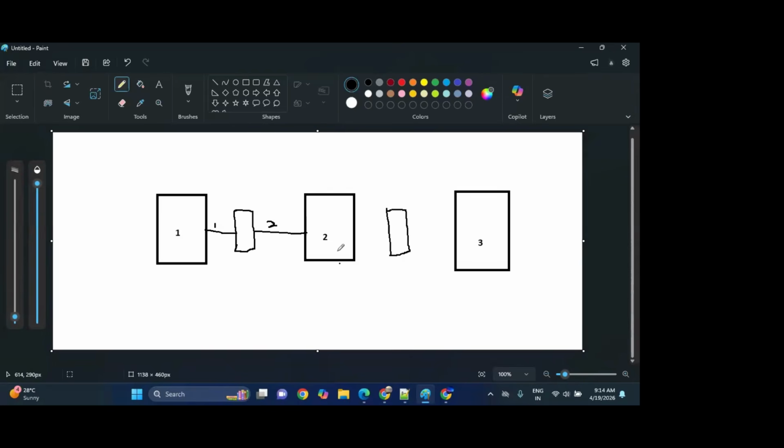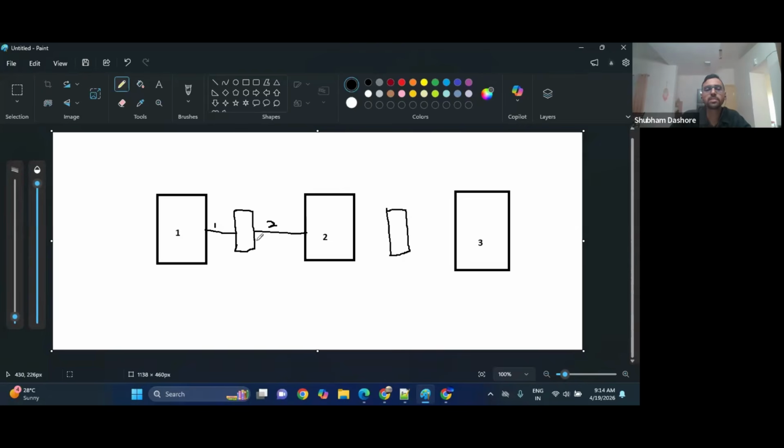So the disadvantage of multi-voltage domain is that we need to add some extra logic like a retention cell and level shifter. These are the level shifters, and the retention cell will eventually increase the area a little bit, and due to the level shifter, a little bit of delay will be there. Delay will increase and area will increase. So these are the things. And what is the function of the level shifter? This is the level shifter.